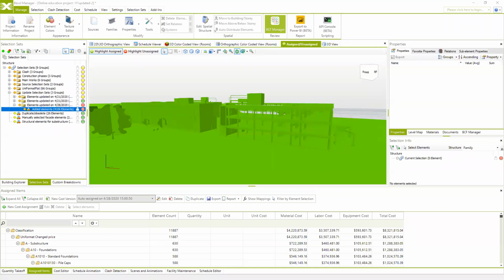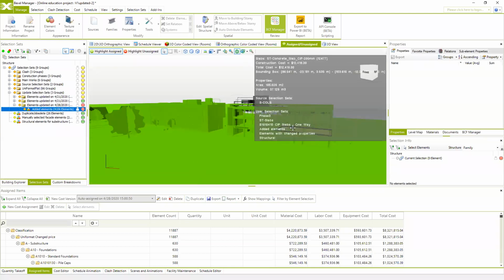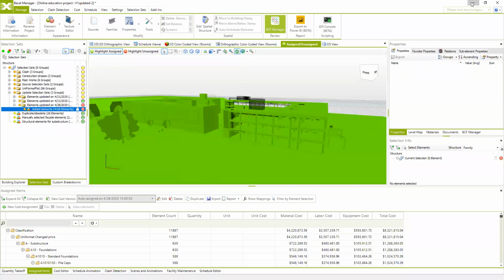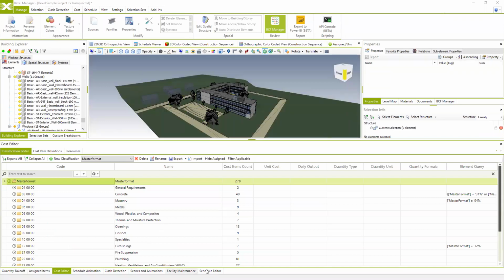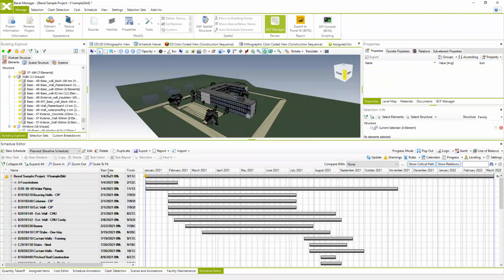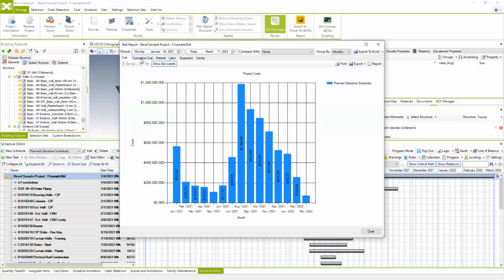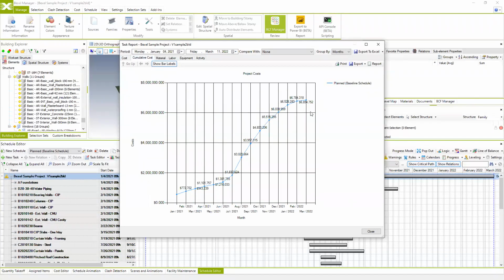We can see the financial flow of the project within the information of the cost structure and the schedule. Yes, of course, and this is something that I'm going to present when I explain how the 5D actually works and how you can link your cost estimation with the schedule. I'm going to briefly show you within this sample model, we have already created schedules, and all these schedules are related to your cost estimation, and you can check task reports with the flows, and you can export all these into Excel spreadsheets.